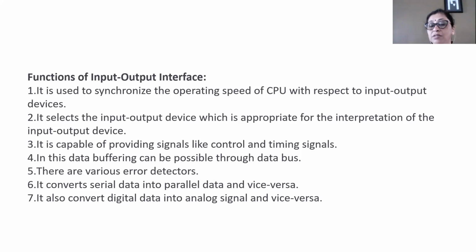Okay. So again, this is done with the help of shift register, which is serial in parallel out. So using this type of register, interface is going to convert the serial data which is available from peripheral device or input output device to a parallel data. Okay, so thus conversion of serial data into parallel or parallel data into serial, this functioning is carried out by the interface.